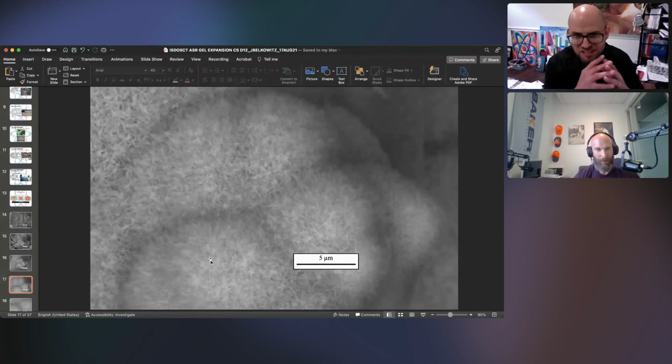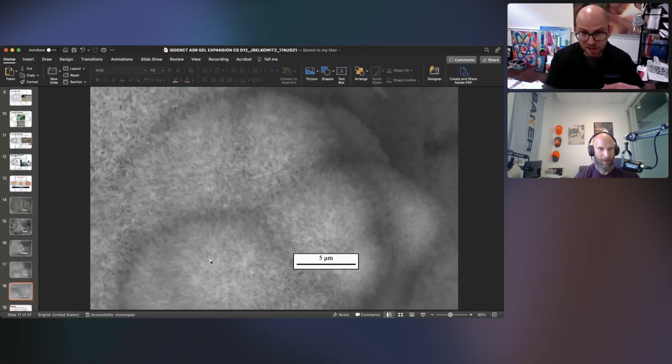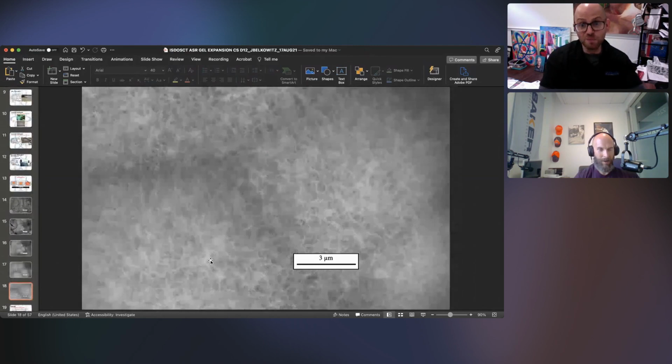And it's those needle-like fibers that create this environment that imbibes or draws more water in, right? These small pores create a capillary suction that draws in water and salt that creates this vicious cycle of more gel growing, right?